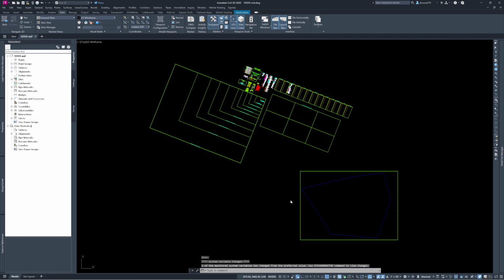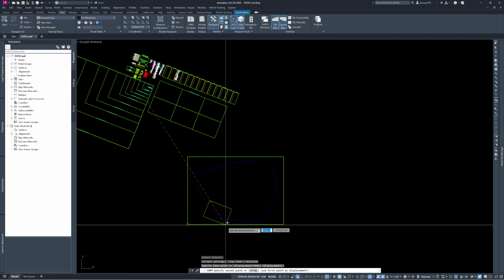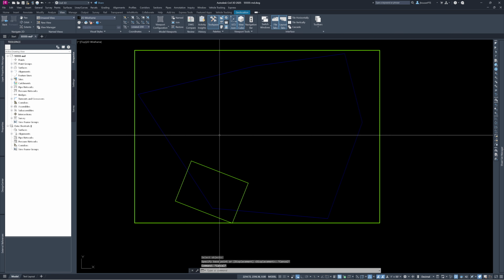Let me see, we could take our, let's say we take 50 scale. We could put this down here. We could say, okay, we're going to have a detailed area. This is going to be a detailed area down here. And, oops, I guess I should have. If I want to keep the same rotation, I can do that. Or I can change it back to world.